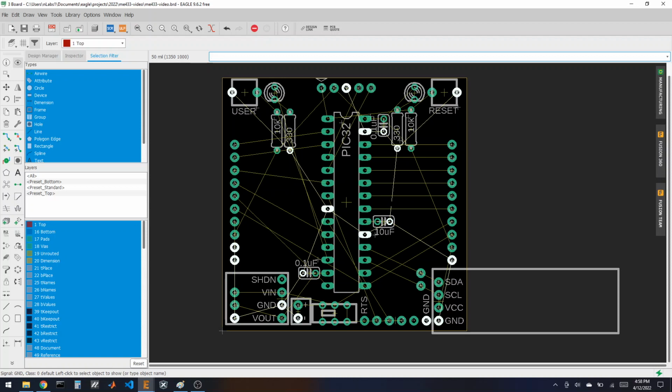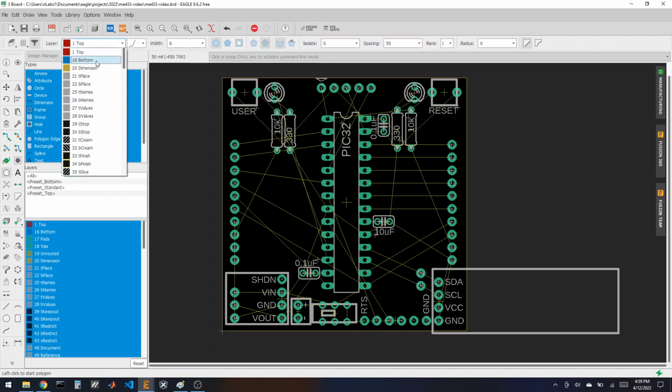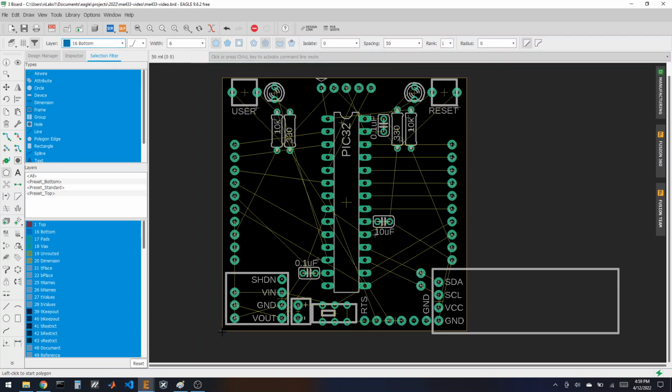Here's the ground connection. So pretty much everything has to get connected to ground somehow. It'd be really nice if those could be automatically connected. And one way to do that is with a ground plane. So the first thing I'll do is connect all the grounds to each other using the polygon tool. I'll grab the polygon, and draw this polygon on the bottom layer of copper. And I'll just draw a big wire all the way around my board.